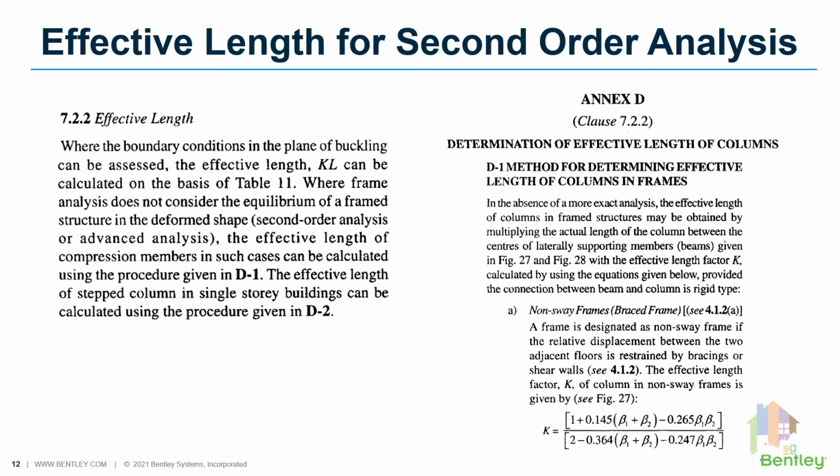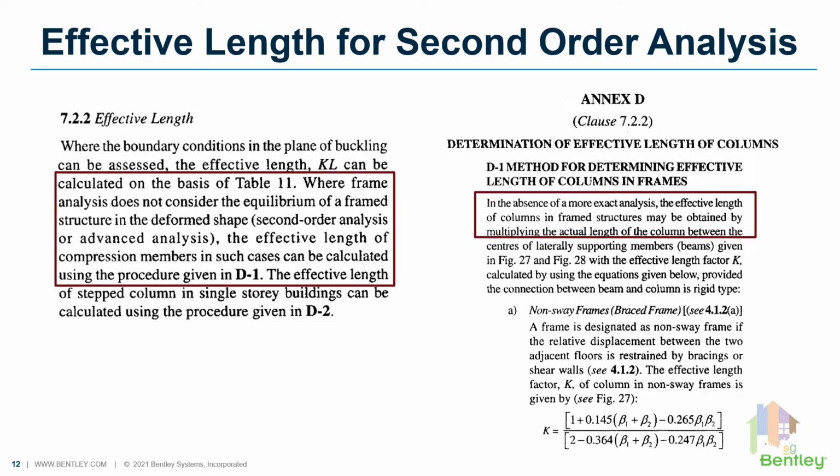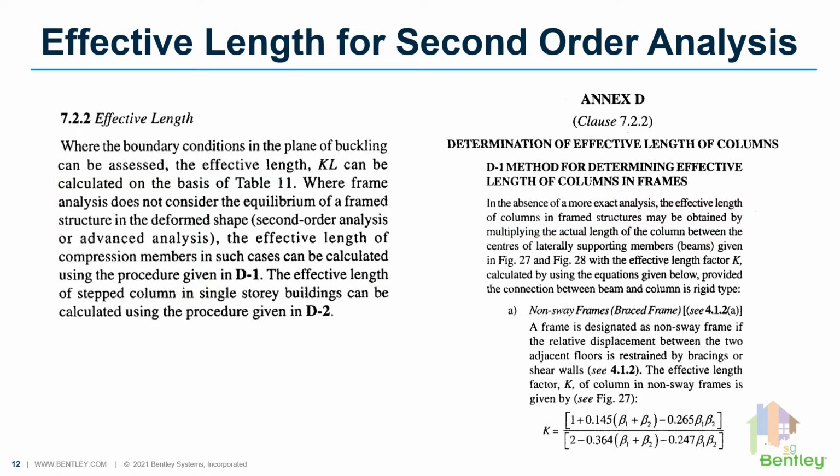In both clause 7.2.2 and Annex D, code suggests to use this approximate approach if deformed shape of frame is not considered during analysis. If you perform second order analysis, then you are actually considering the second order effects and additional moment generated due to deformed shape in analysis and design. In this case, whether we need to consider the effective length factor or not, code is silent about that.